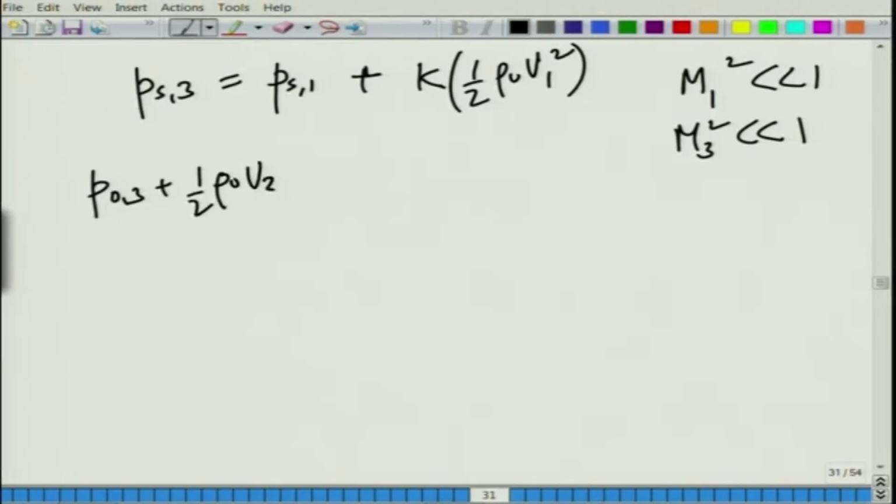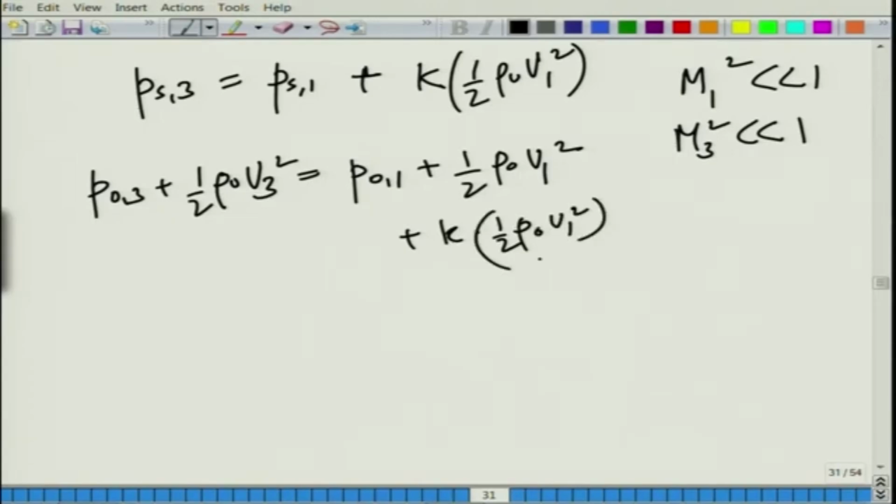Now, if we were to expand this stagnation pressure into the pressure plus the velocity contribution due to the velocity head, here we have this, because stagnation pressure is equal to the pressure in the fluid plus half rho u squared term. Now this loss coefficient, I will probably present a table later, but what we immediately need to do is, since we are doing acoustics, apply some perturbation. So, this equation needs to be perturbed.